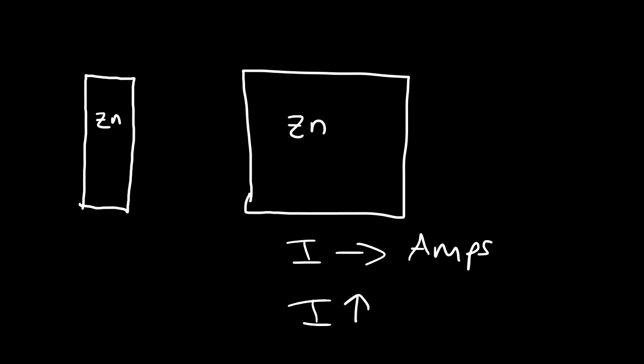Now if you have a metal electrode, it may not be practical to increase the area of that. So what some batteries have is, instead of just a metallic electrode, sometimes the electrode can be pressurized into a powdered form. So let's say you use a powdered form of zinc or a powdered form of graphite as an electrode and you pressurize it, you can get a lot more surface area that way, and so you can get a battery that can deliver a high current.